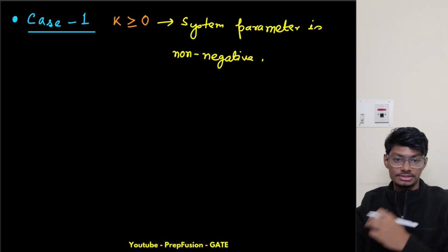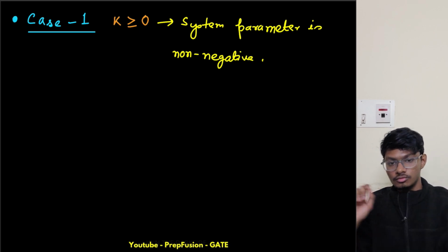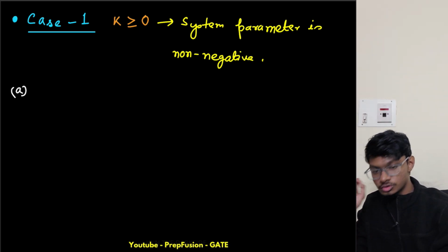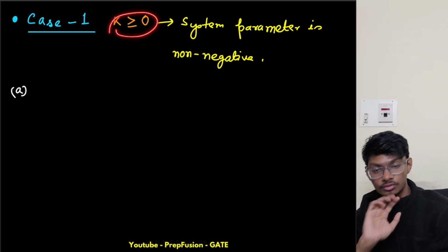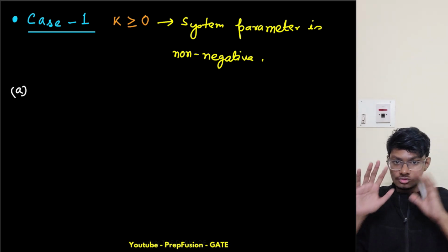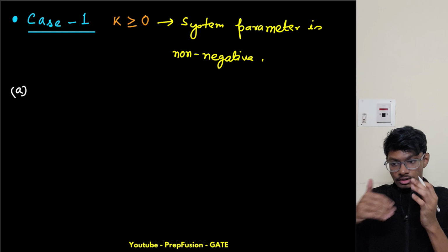First there are two cases. So first we'll do case 1. What we'll do is find the closed loop poles when my k is tending to 0. Obviously it is not equal to 0. We'll choose two extreme points and try to find out our closed loop poles. This is how we start a root locus.